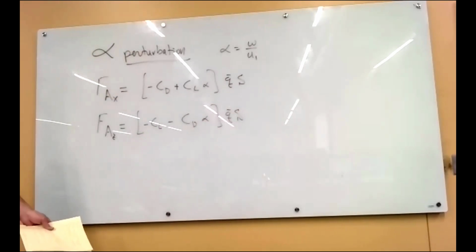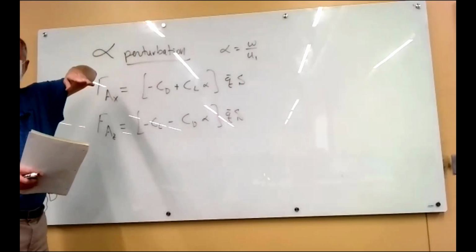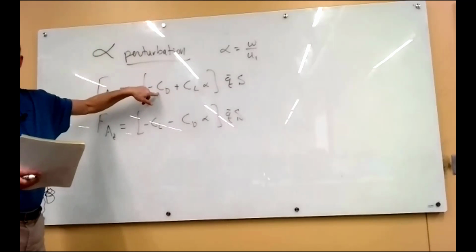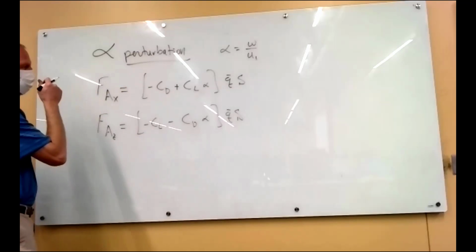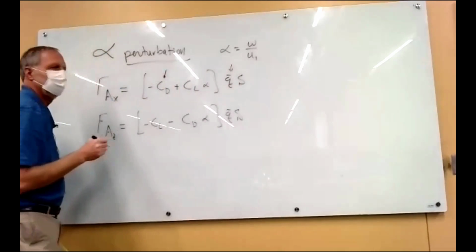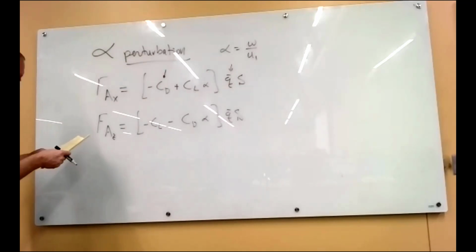And again, a reminder, where did these come from? It comes from the fact that when we're tilted down at that little angle of attack perturbation, then we have components of CL and CD in different directions. And the U derivatives were complicated because we had to take the derivative of Q bar and this stuff over here. Now we don't. So this is a lot easier.